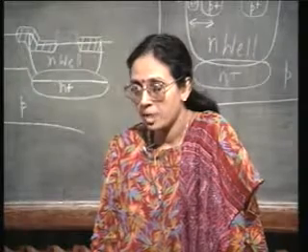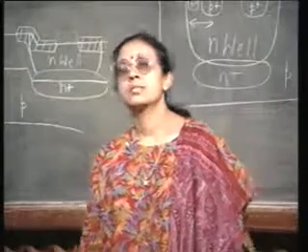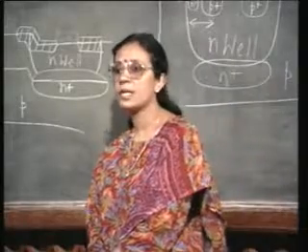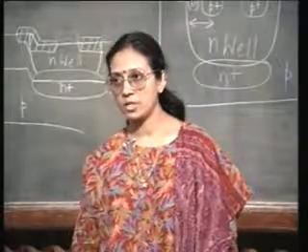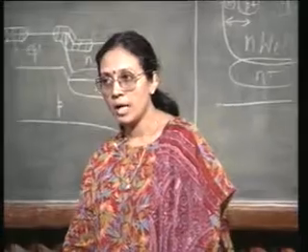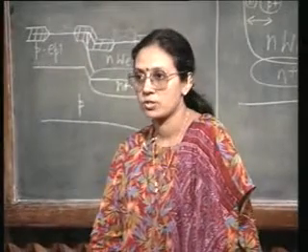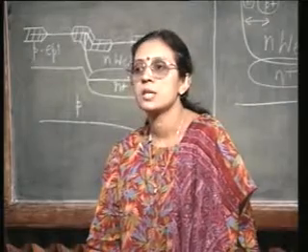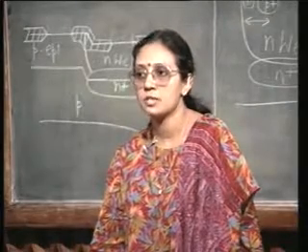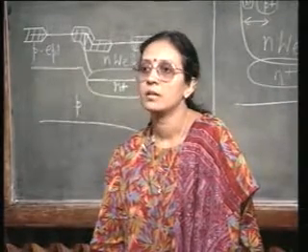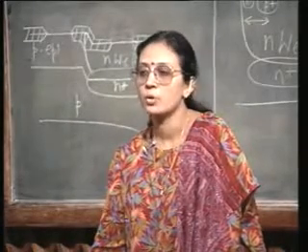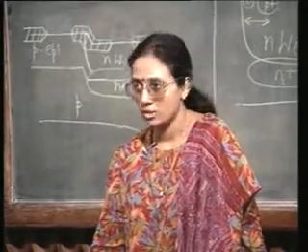Okay. So, BiCMOS is essentially going to occupy a niche market for very high performance circuitry at a competitive cost, right. You are going to use ECL or bipolar junction transistors at the points where you require high speed, and you are going to use CMOS in the rest of the circuit.